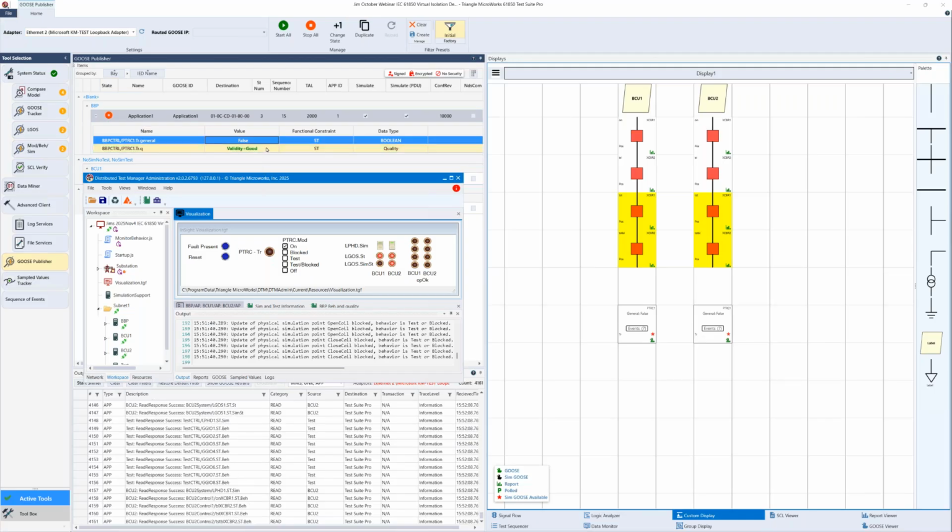Now while we are publishing the simulated message, we can see if the normal message still works on VCU1. I can now also create the fault from VCU1, and we see VCU1 still reacts on the normal message, but not VCU2, which is now looking at the simulated message. And I can again reset.